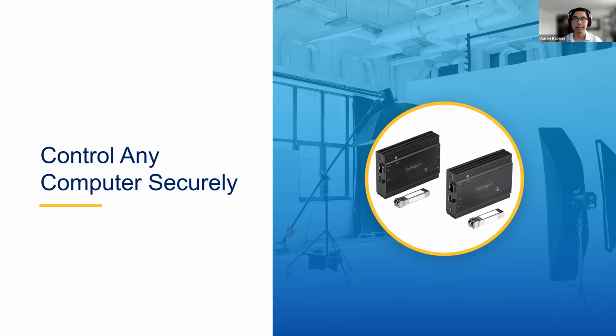Not complicated at all, actually. Pretty much the kit comes with almost everything you need. You just need to supply your own fiber optic cable, but you can easily connect it to the included SFP transceivers. There's also no software required or network settings that need to be configured. The one convenient feature of this is that it comes with open SFP+ slots, so you can trade out the multi-mode transceivers that come with it for single mode and get up to 1,600 feet of range.